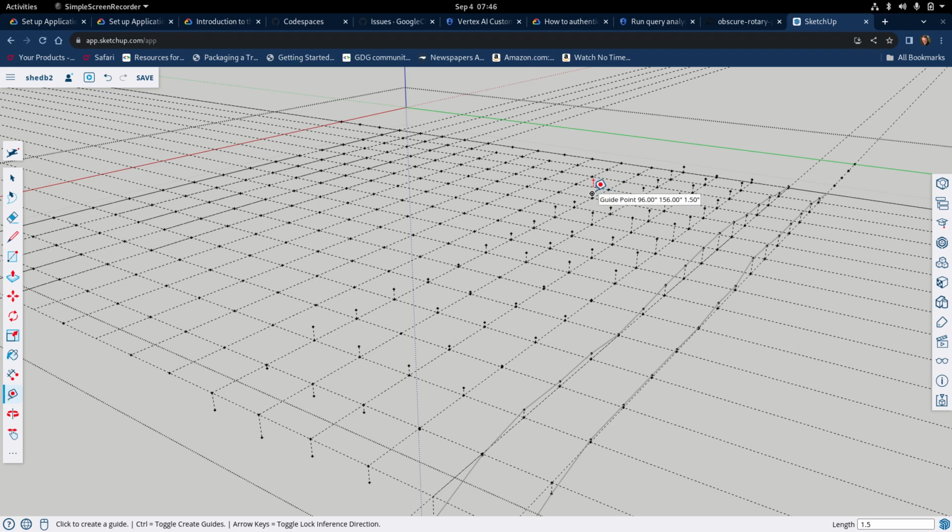And if I look here, one of the other things about this is if I want to see how far this grid line has been offset to the right, when I hover over it, it'll say minus 4.5, and that's accurate for that particular measurement. For whatever reason, it doesn't show it if you click the select item and click it.